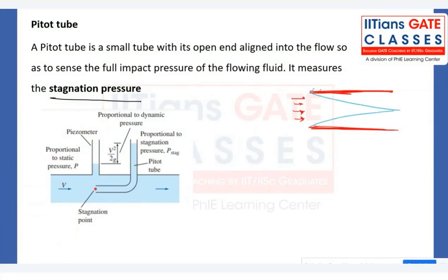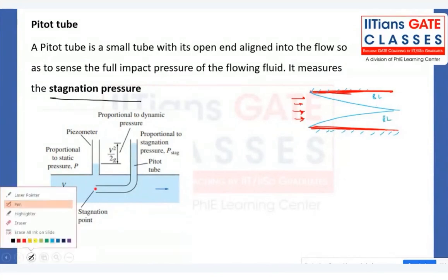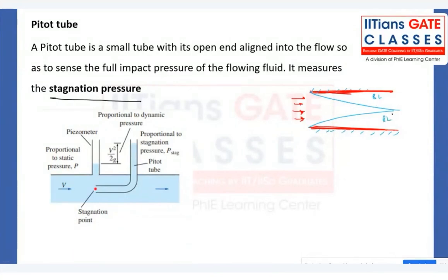You can consider it like a two plate system. So fluid flowing in a pipe, you can consider two parallel plates, where from both the plates there is some boundary layer formation, right? When they merge at the center line, then only we will be having fully developed flow regions.